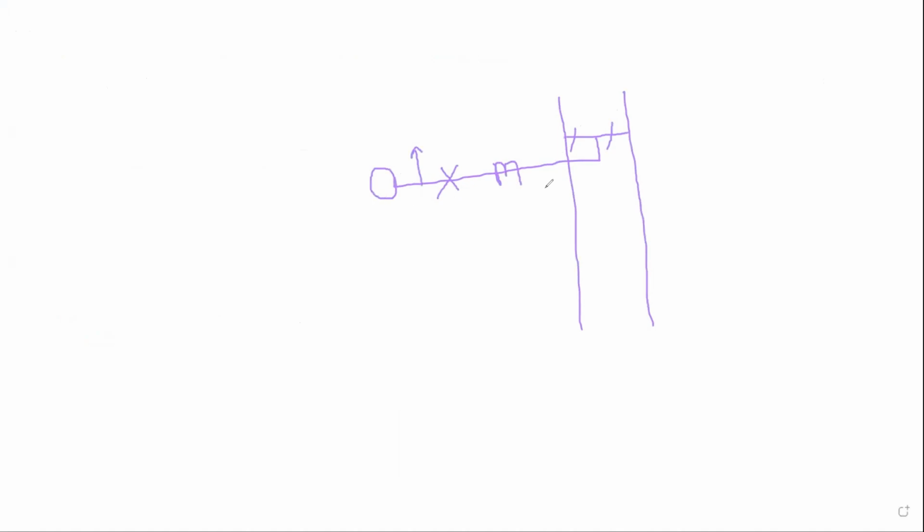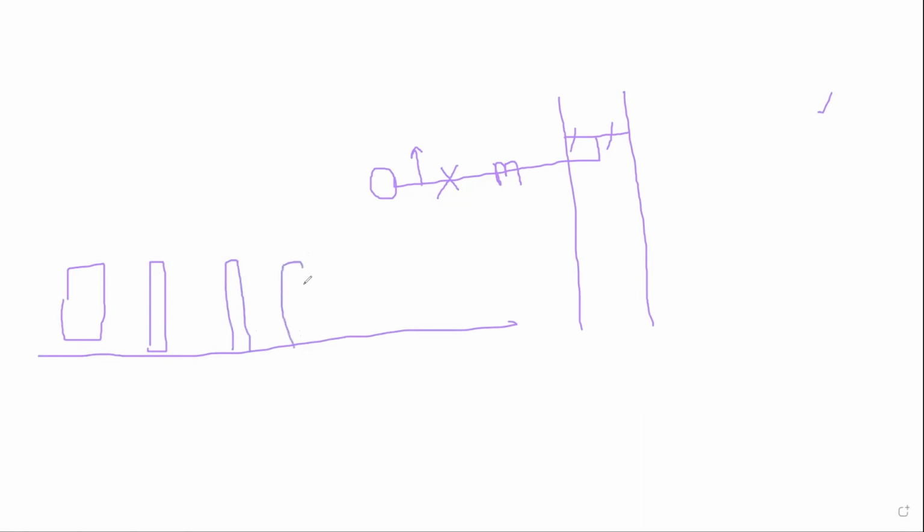Now, if I want to erect this same arrangement in the substation, how do I do it? I will place the transformer, the lightning arrestor, the CT, and the breaker, and this bus I have to do. I am laying two towers like this.